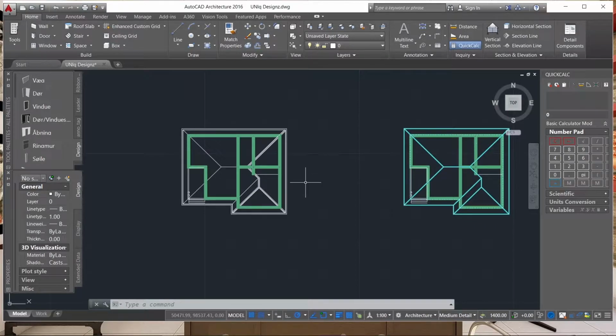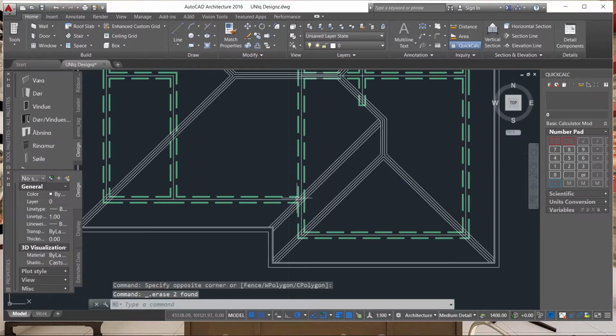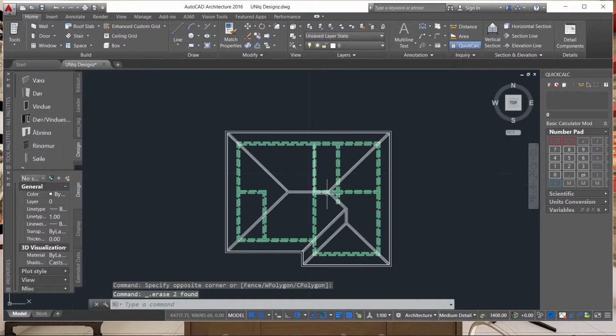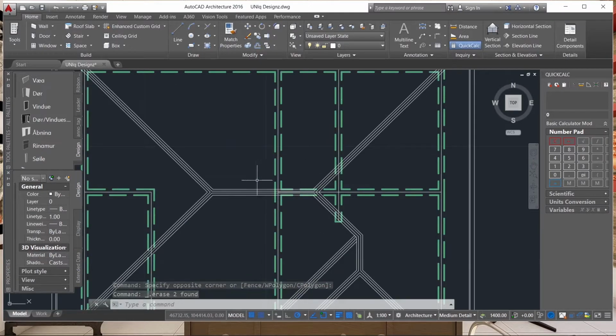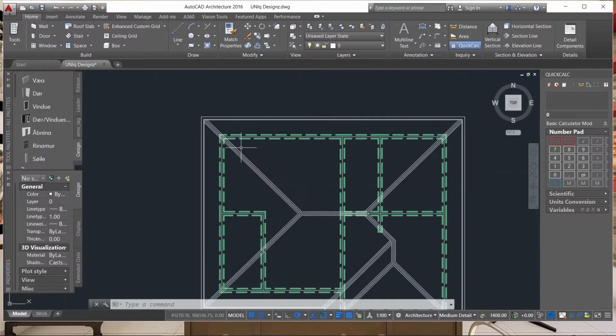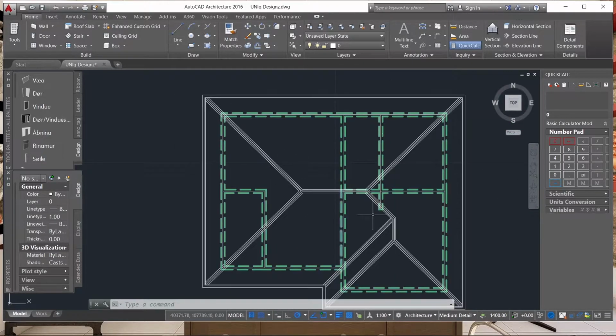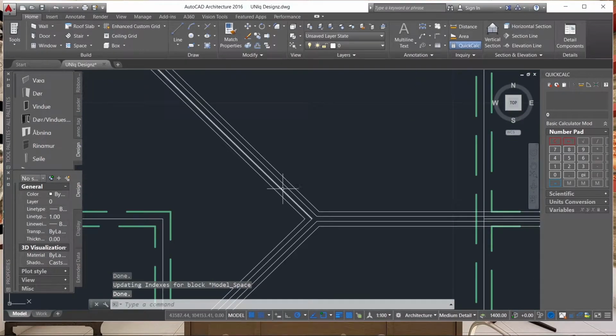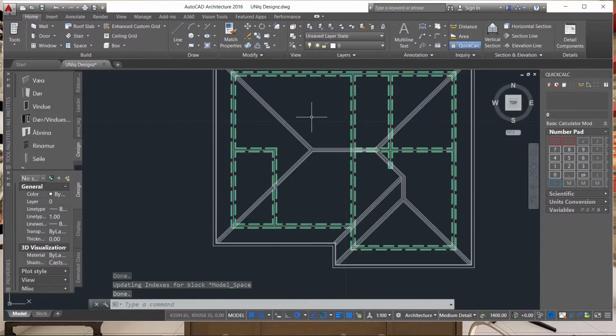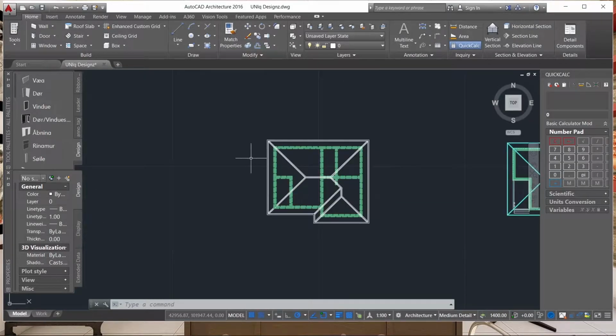After the detailing, there is some block work below. That's the reason for the short dashes. So after doing everything, this is how your results will be. You select the walls, then you change them to short dashes, then you do the offsets, that's the 25 and then the 50 offset distance for all the ridge lines. So this will be your results.